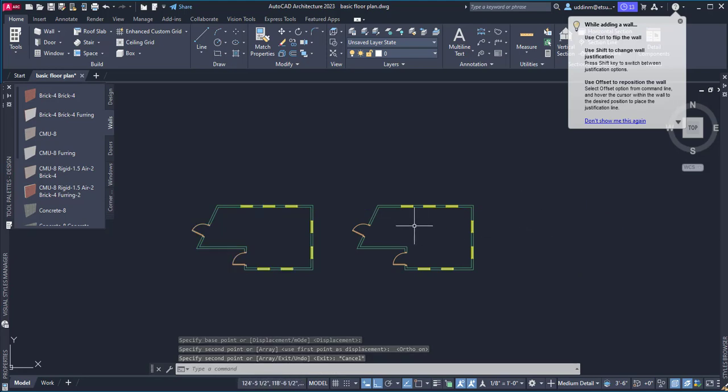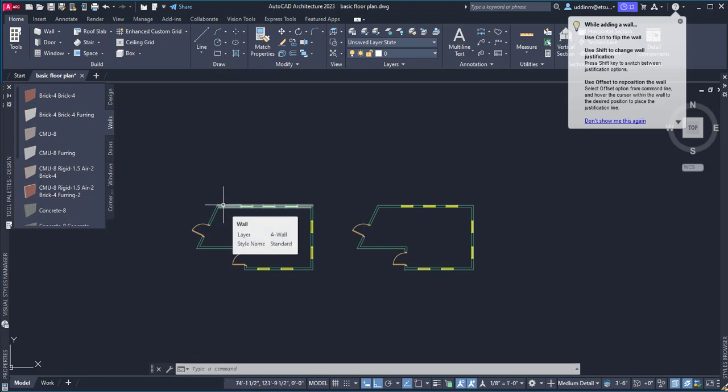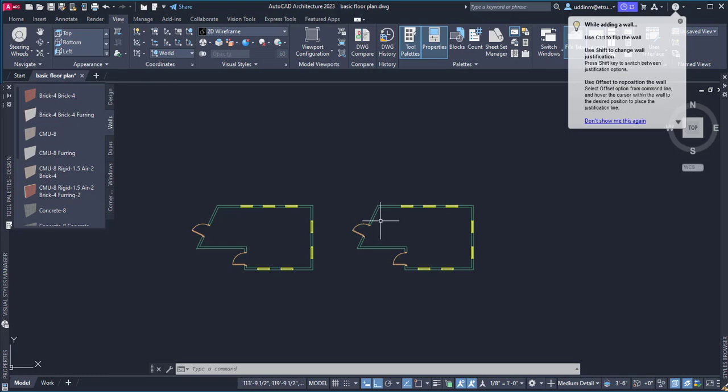Now, as you can see here, this is a top view of the drawing, and therefore we can't determine, or at least see, height here. Unless we select a line and go to the properties dialog box and see it that way, but physically see it, you can't see height in the top view. So what we need to do is go to view and choose a view that we can see the height, since we want to take this second floor and move it up onto the top of the first floor.